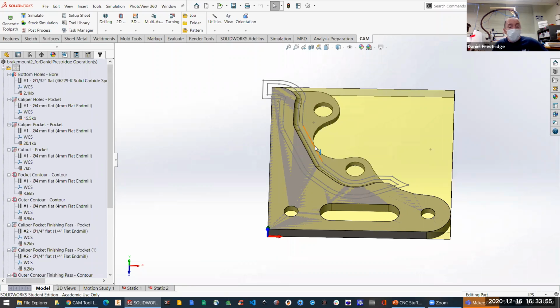Or, because this is an upcut, it pulls up on the material, and if it pulls up to the point where it dissociates itself from the machine, then it has the potential to launch those pieces into your general vicinity at very high speed. So this is one thing to really pay attention to.